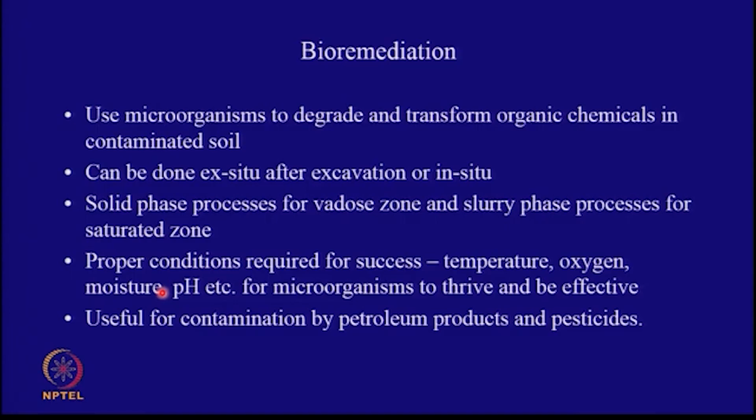All bioremediation exercises are not successful because you may start with the proper conditions, but you may not be able to maintain them. So, temperature, oxygen, moisture, pH, etc. are very important for the microorganisms to thrive and be effective. But they have been found useful for contamination which has been caused by petroleum products and by pesticides.